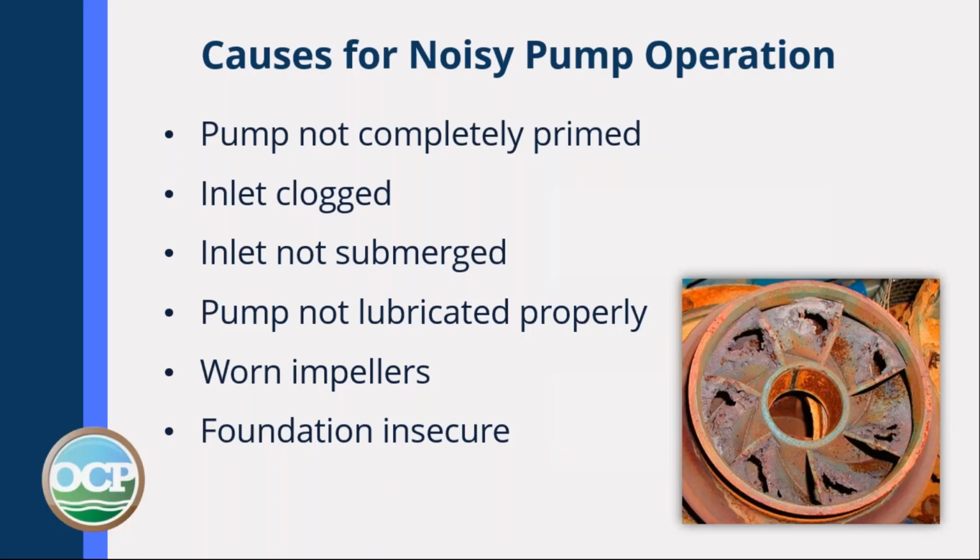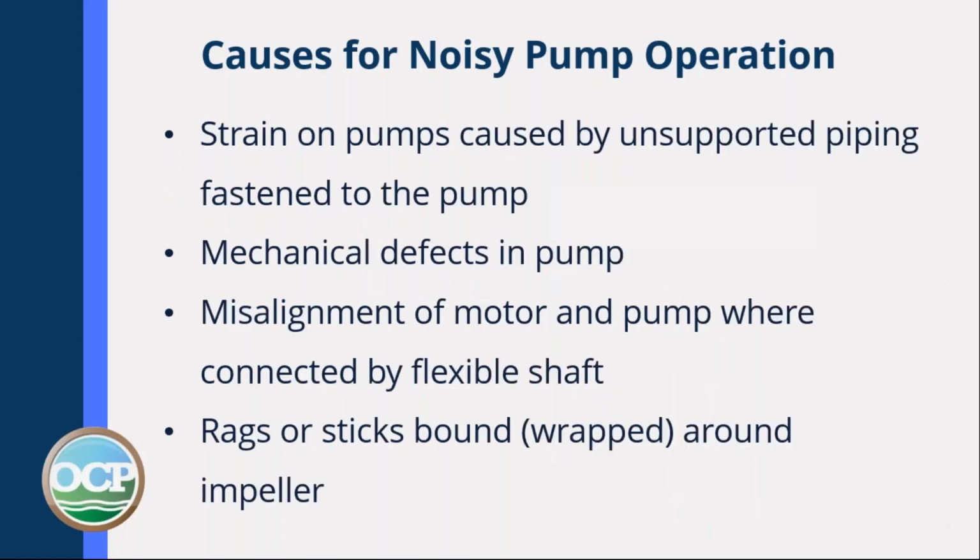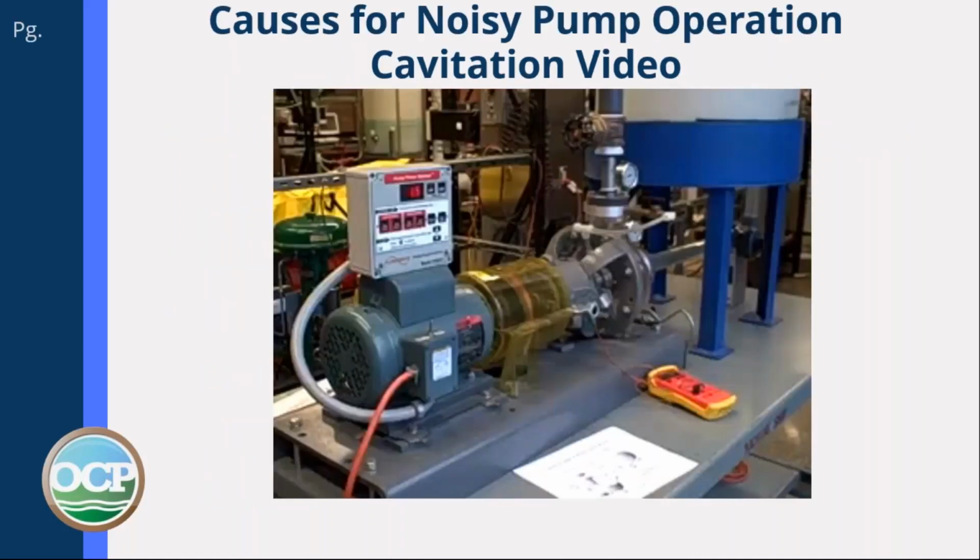The foundation's insecure. There's strain on the pump caused by unsupported piping fastened to the pump. If you've got piping coming off a pump, that piping needs to be supported. There could be mechanical defects in the pump. Could be a misalignment of motor and pump where connected by a flexible shaft. There could be rags or sticks wrapped around the impeller. And it could be caused by cavitation.